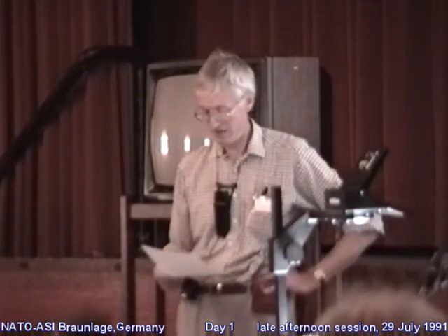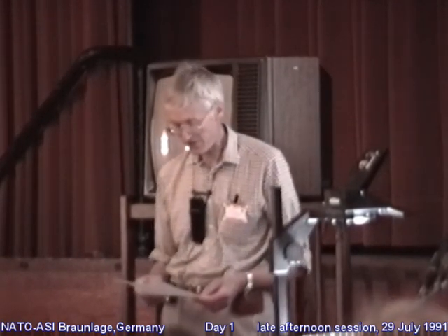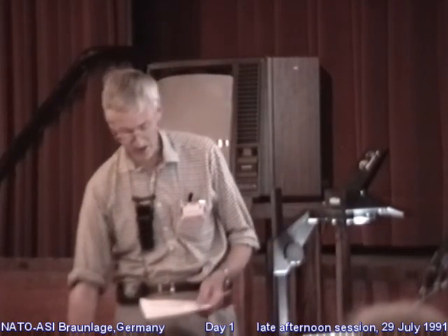As you realize, this is very much another introductory lecture, in that I'm not talking primarily about friction. But all the same, whatever type of friction we're concerned with, a satisfactory model of friction obviously must account for data of two sorts. Firstly, the magnitude of the frictional force that's transmitted across the interface, and secondly, the rate at which mechanical work is dissipated through friction. Both these quantities may or may not depend upon the presence and the magnitude of some kind of adhesive force, such as intermolecular attraction across the interface.